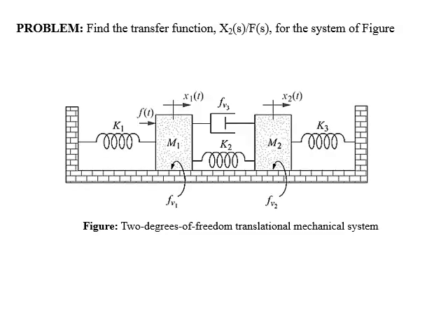Dear students, now with the help of an example, we'll study how to find transfer function of a mechanical system. In this example, you have to find transfer function X2(s) over F(s). If we look at the figure, in this system we have two masses M1 and M2. M1 is moving in the direction of x1, whereas M2 is moving in the direction of x2, which means that their direction is already defined. The externally applied force f(t) is acting on object M1.